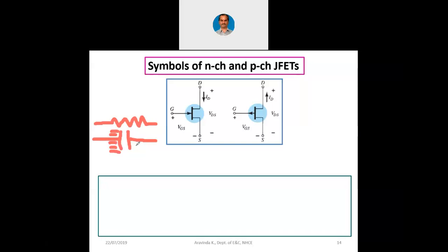So what happens is, because there are electrons here, because of electrostatic induction, at the other plate there will be positive charges or holes. At the other side there will be a deficiency of electrons. When there are more and more electrons at the left side plate, these electrons will repel the electrons which are on the other side. So when the electrons leave this particular plate which is opposite, naturally there will be holes induced. This is called electrostatic induction. When there are holes induced, we say that the medium in between is called a dielectric medium. Di means two. We call it dielectric medium because there is an induction of minus and plus at both sides. There is an induction of electrostatic charge. That is when you say the capacitor gets charged.